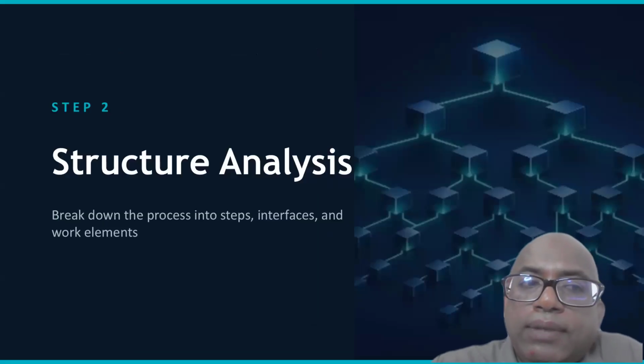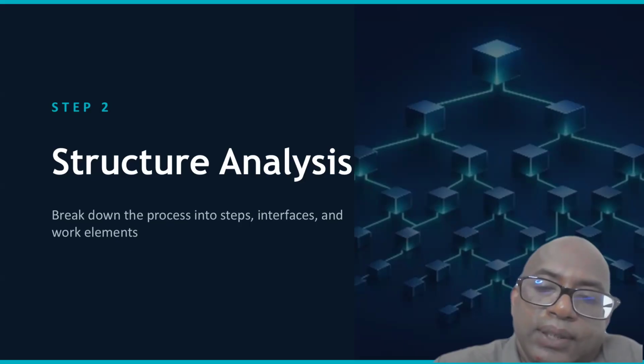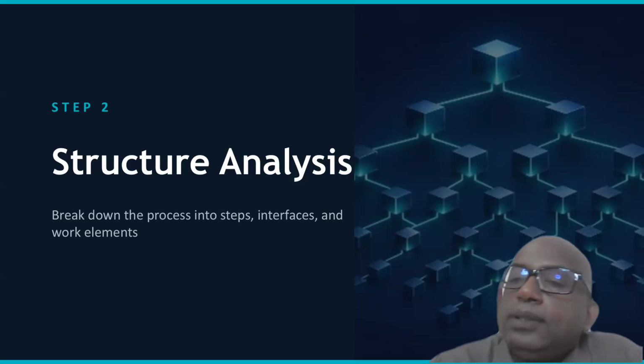Okay, then the next one, step 2, is the structure analysis. This is one of the very important steps in the AIAG VDA PFMEA version. Break down the process into steps, interfaces, and work elements. This is very important. We are not talking about the process generally.